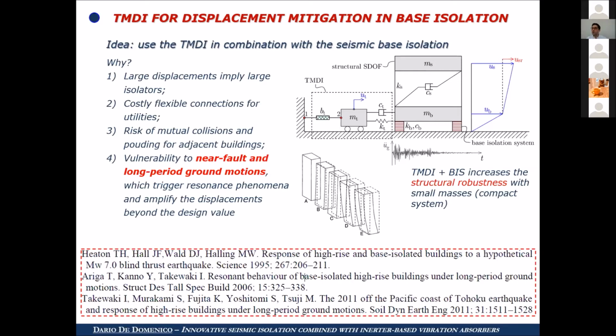It also reduces the vulnerability to particular classes of ground motion, in particular near-fault and long-period ground motion, that can trigger resonance phenomena and amplify the displacement of the isolation system.